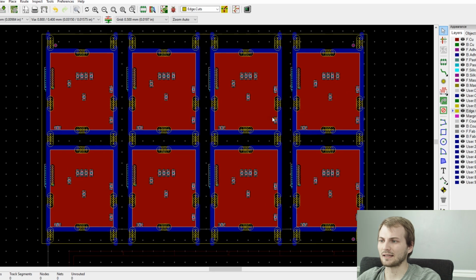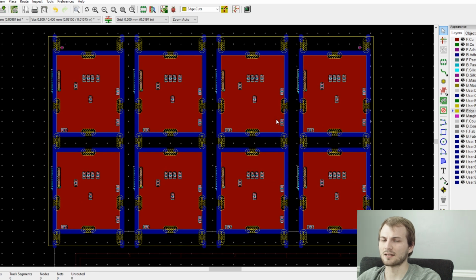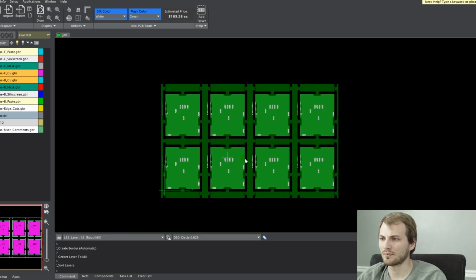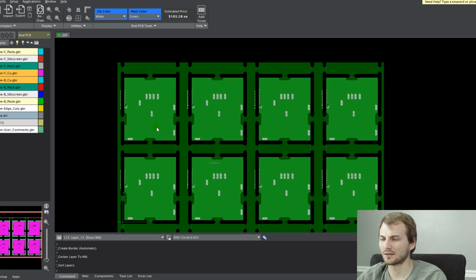So now the last thing I will do is import this into Fab 3000, which is a Gerber DFM tool, and it'll visualize what the board actually looks like with the routed edge. And I think that'll better explain how this actually will work and how you depanelize it. Okay, so here's the panel now imported, so you can see now physically what this will look like.